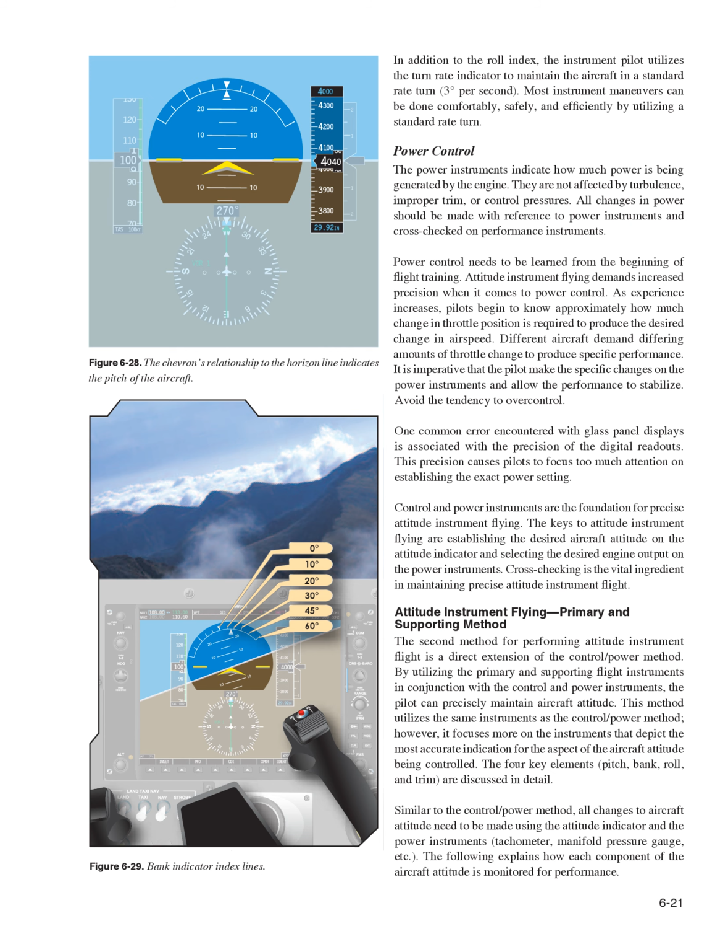In addition to the roll index, the instrument pilot utilizes the turn rate indicator to maintain the aircraft in a standard rate turn, 3 degrees per second. Most instrument maneuvers can be done comfortably, safely, and efficiently by utilizing a standard rate turn.